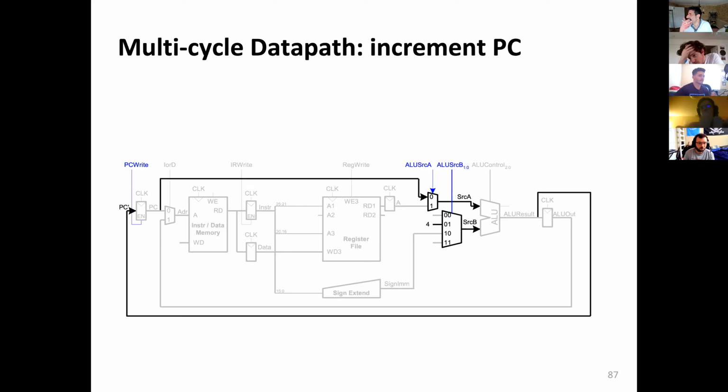Let me also ask this: could we add these new flip-flops in single cycle too? Would things go wrong or not? I don't think you are able to add them in single cycle, because single cycle depends on everything having constant control signal outputs. It depends on all the parts being synchronized during that one cycle and then resetting after it. So if we start playing with the cycles in single cycle architecture, it won't work.